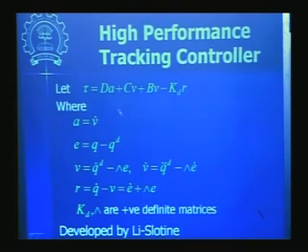So D times this term is in some sense your computed torque, if you recall, the inertia part of the computed torque. Similarly, C times this qd dot term will be again in some sense your computed torque, or the C part of the computed torque trajectory, okay.